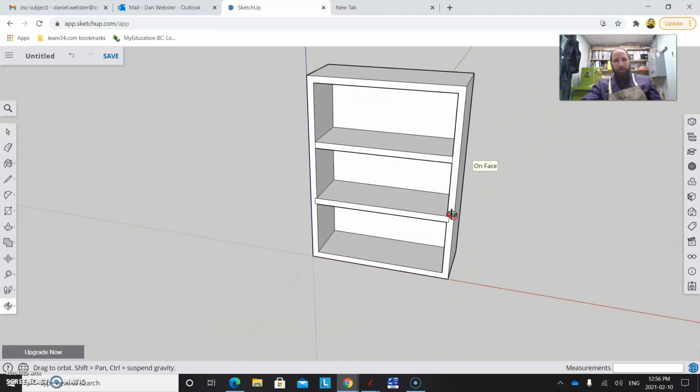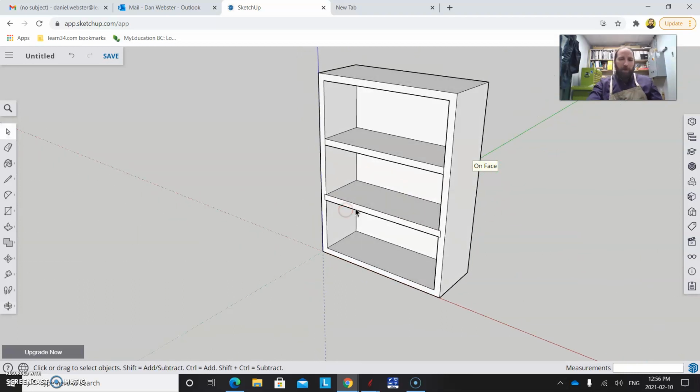Okay, so it's working out so far. When I build a cabinet like this, if I'm putting a door on it, I like to put a little bit of a trim piece on the sides. This is going to work because that cabinet is a component. If you didn't turn that into a component, this next step will drive you mental. It'll drive you nuts. So I'm just going to make two trim pieces, 600 millimeters by 50 millimeters.